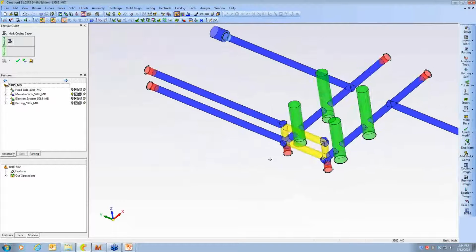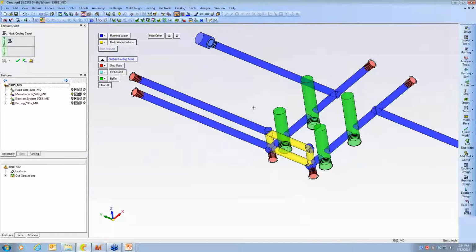While something like this might be intentional, it's more likely that a line has been drilled too far, or that an extra plug was left over from some change. Either way, identifying this problem now allows the design to be corrected before the drilling gets done in the shop, and that's important.